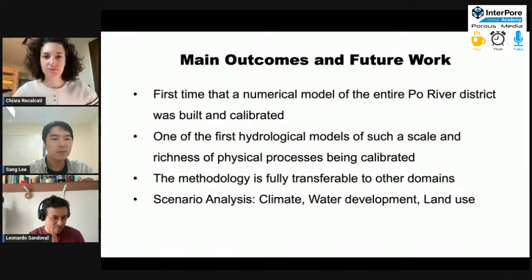It is a bit of luck, I have to say, but also all the information that we used to construct this first model was built upon the base of previous research. So the first value of hydraulic conductivity that we used was actually taken from previous research on the hydraulic conductivity parameters in general, of the different geomaterials. And the same happened with, for example, the van Genuchten parameters. We didn't have a value for the area, but we have values reported in other systems in other parts of the world. So we used those values, which were